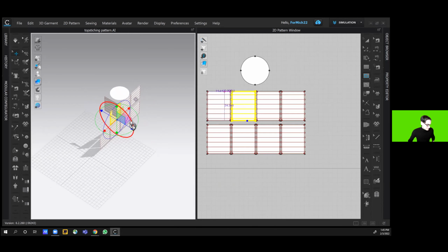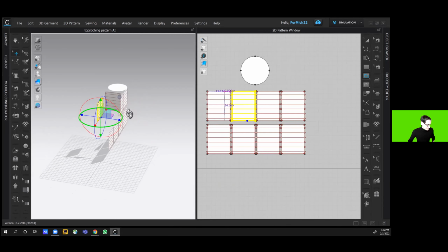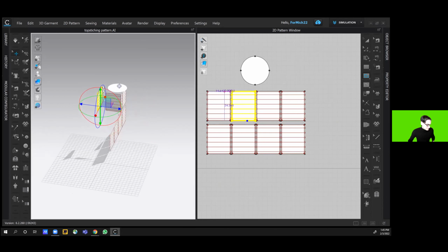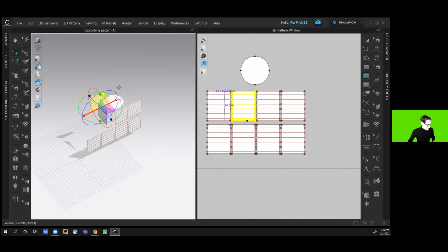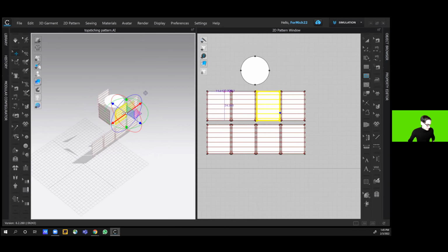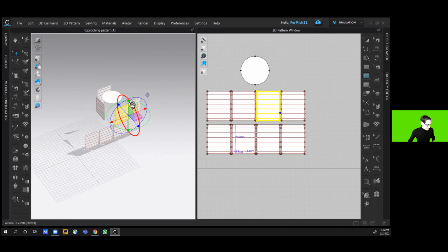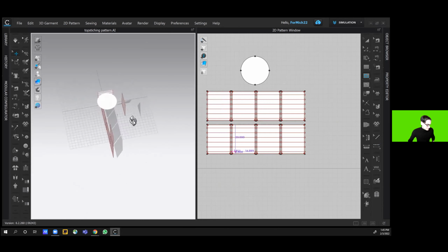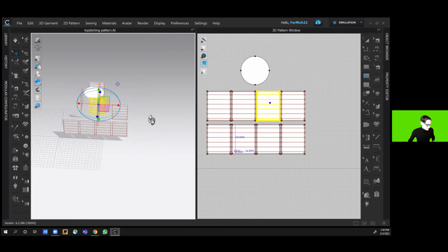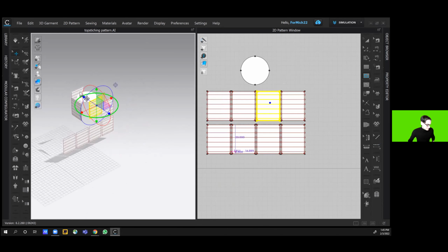Let's say you made a pattern fully in Clo and you didn't touch Rhino at all, but you want to get the pattern out into Rhino or into Illustrator to produce a drawing with it. I'll show you how to export from this 2D viewport to get all the line work as vectors. So you can truly move between Rhino and Clo quite fluidly, even in 2-dimensional space, which is exciting.